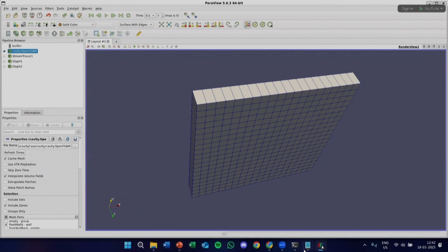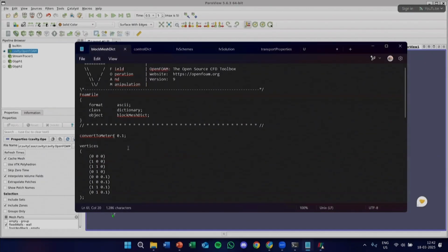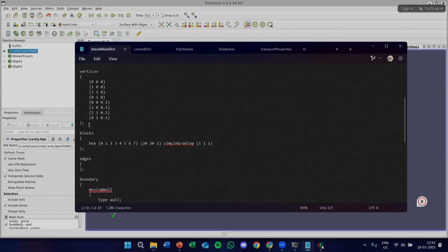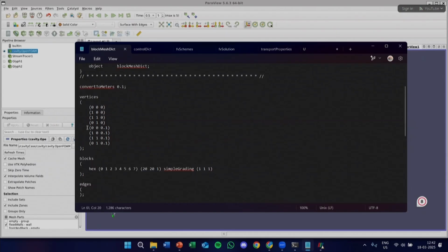Okay, so you can open your blockMeshDict and go to line number 19 and see if there's anything typed wrong or something. That's the only error, right? Because I checked there also, but I don't seem to see anything. Okay, just confirm if there is some semicolon or something missing. Because just like normal C++ code, if your semicolon or something is missing, it will give you an error. Sometimes by mistake, if you backspaced it or something, that might be the problem.